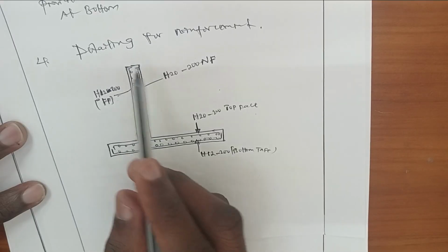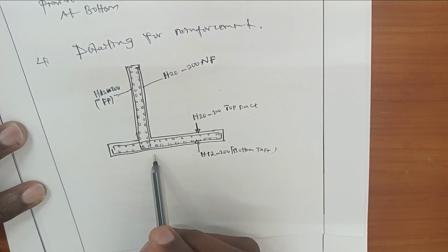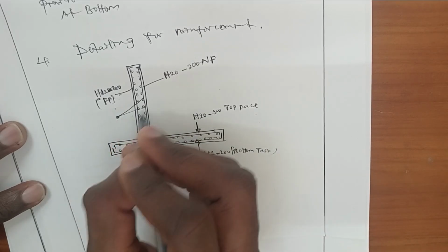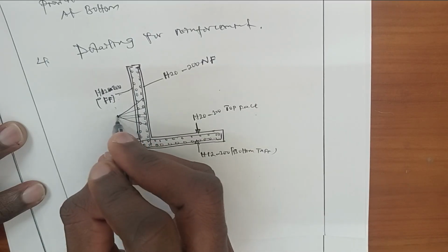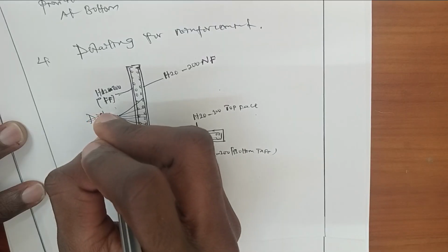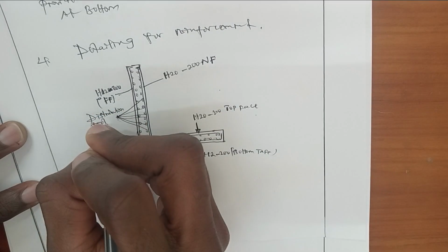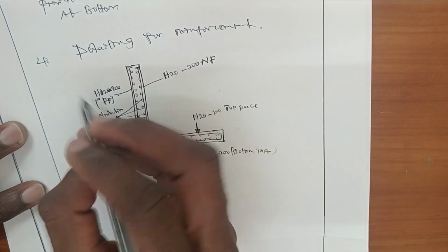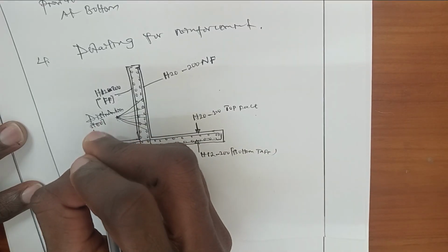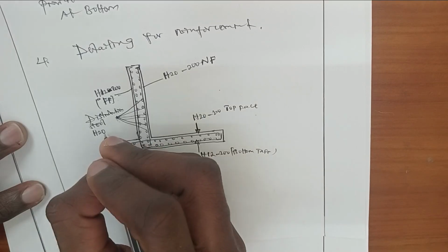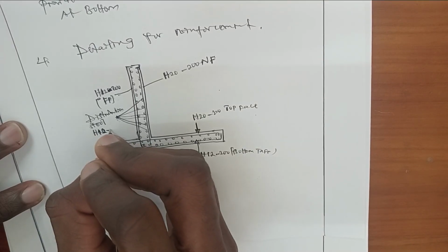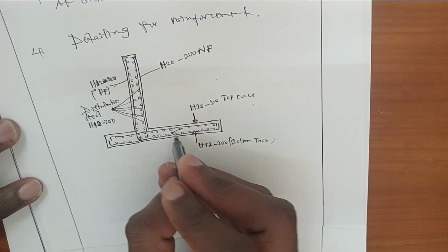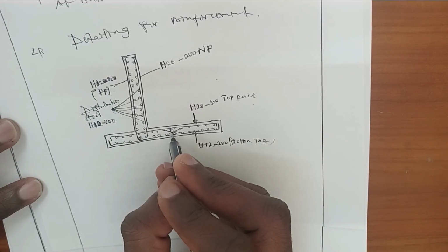Also, this steel acts as distribution steel for both stem and base. This toe provides distribution steel, which distributes both top and bottom. This distribution steel gives the minimum area, with high strength bars of 12 millimeter at a spacing of 200 millimeter, as well as for the base, where the distribution steel is provided in both bottom and top.